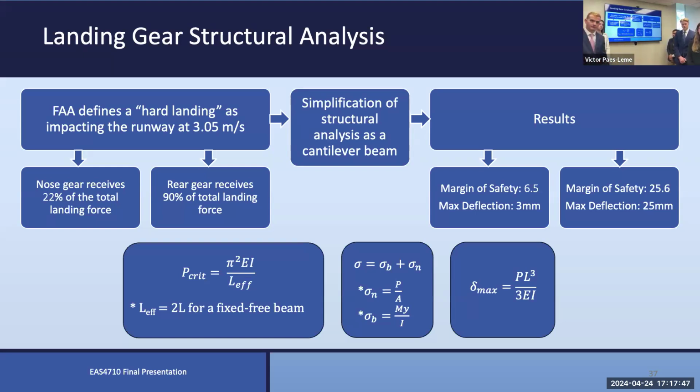And one thing I want to say is that when you use that maximum deflection, it's assuming that your structure is in this direction. You know what I mean? The equation is for a cantilever beam, and the force is applied this way. Now your actual landing gear is in this way, and the force is applied this way. So there should be some difference.